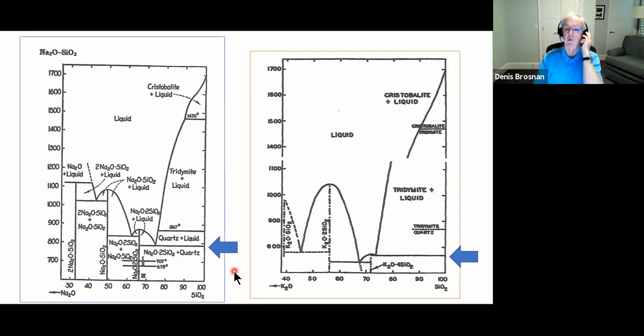So guess what? In the prior diagram, I said the two-component alumina silica diagram was insufficient to explain what happens in firing. Well, that's because these materials contain some fluxes, alkalis, that increase the melted phase at much lower temperatures than predicted by the two-component diagram by itself. So you can get an idea that these two-component diagrams are helping us understand where some liquid formation takes place.